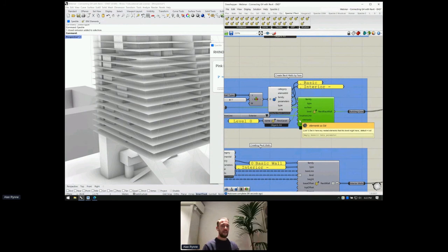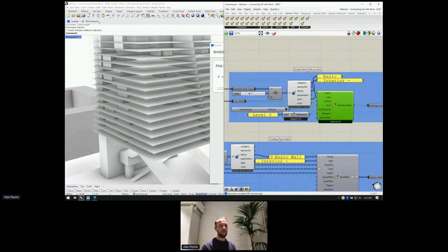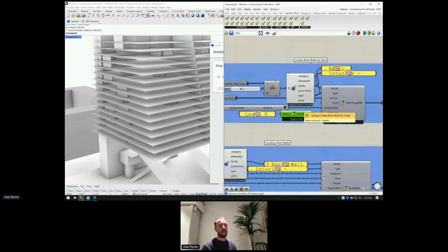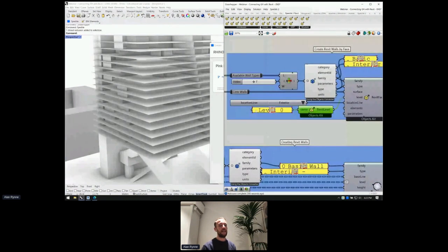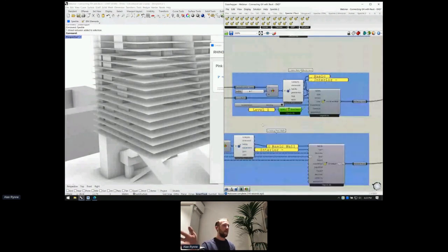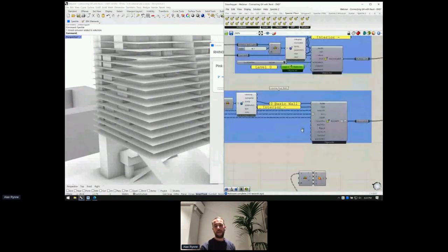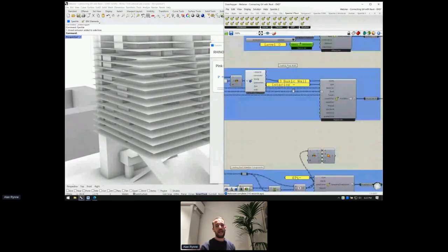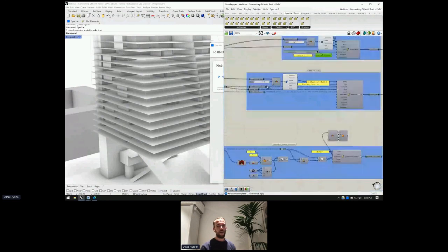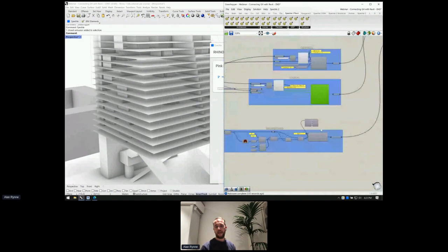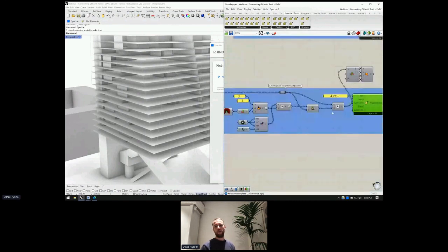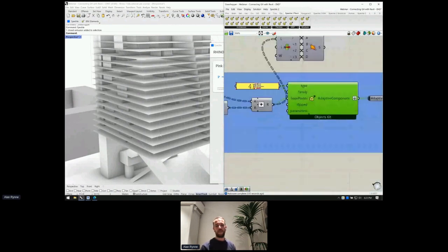In the end file, you also have an example of how to create a Revit face wall using a weird curvy wall as opposed to just a straight line classic wall, which also has a level attached. So you can automatically attach a level just by a name if you know that level exists in Revit already. And you also have the actual connection to do the Revit walls entirely, and what I was going to get to, which is the adaptive components.